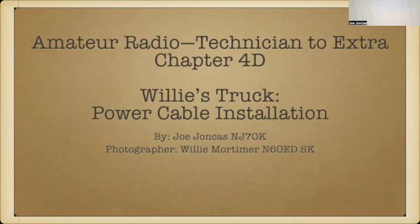there's a number of things I want to talk about. One is the length of the wire in the battery terminal. The reason I wanted them short is to ensure that those wires could not short onto anything between the battery and the fuse. And in that situation, I needed them to be short.